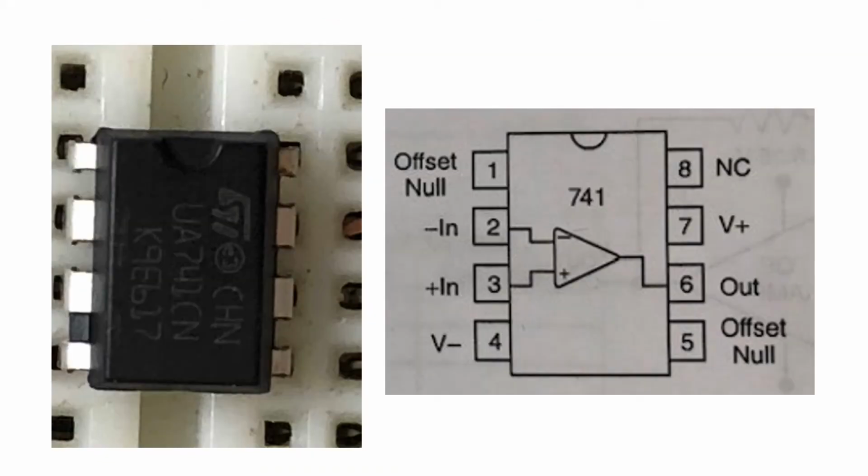If you were to look at the actual chip, and I've kind of zoomed in on it here, you can see it's got all sorts of numbers and symbols on it. Kind of buried in there is the number 741. The other numbers and symbols have to do with how much temperature range that particular chip can take. Also, what kind of power can it take before it overheats and melts, and they will overheat, and they smell really terrible when you do it. And remember, if it does start to burn and you see brown singeing on it or anything like that, just turn the power off right away.